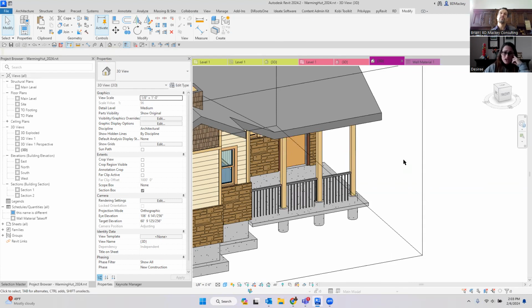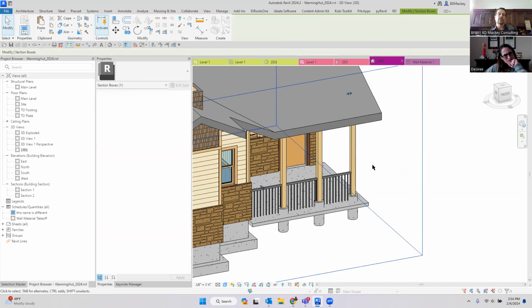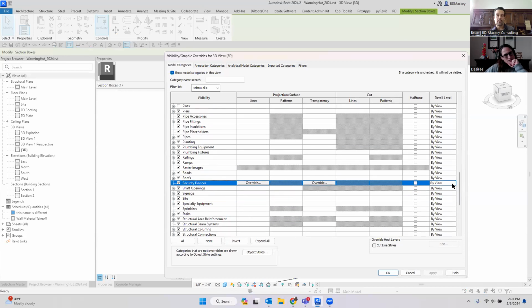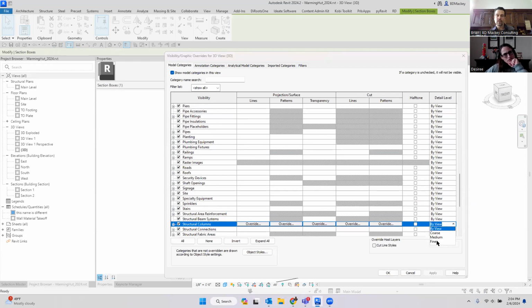Or you're seeing structural engineers, but that's not something likely that we would do. You create a bunch of subcategories. It is for a lot of structural engineers, but more than likely it's because they're actually seeing the 2D geometry. The other thing to look at is, can you make sure that columns in VG are set to be fine? So if you go into structural columns, you always can come over here on the far right side of anything, and you can say, I want those elements to be fine, because you're probably looking at yours in coarse or medium, and you're actually probably seeing the 2D line work of that family, not the actual 3D objects of the family. Because most structural engineers in medium or fine show 2D line work, not the 3D modeled objects. So that would be my guess.